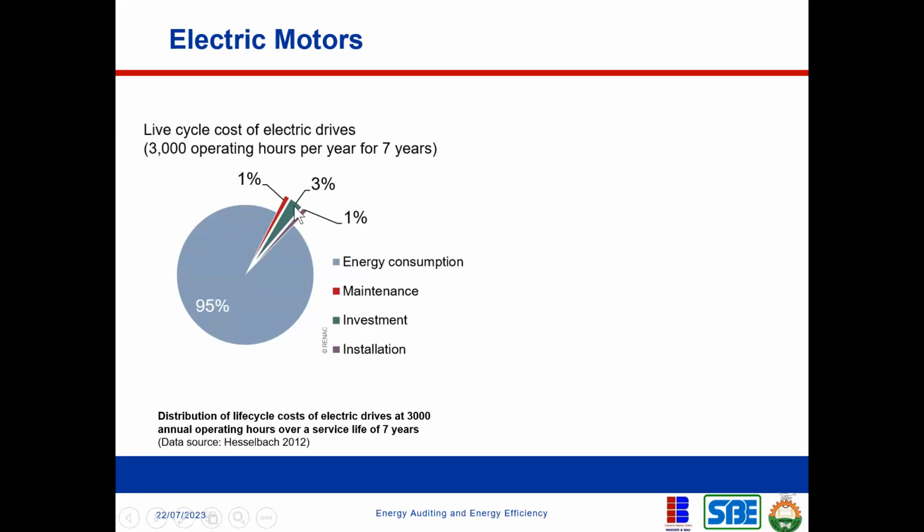So when you're buying a motor, it's very, very critical to look at the efficiency factor of the motor that you're buying, because every improvement in efficiency will save a lot of money over the lifetime of that motor. It might be slightly expensive, but if you look at the cost of buying electricity to run those motors, you find out that you're saving far much more.